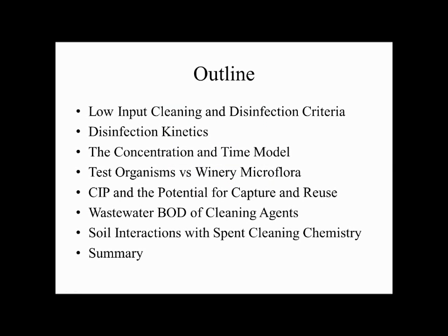Talk about the organisms that are typically used in cleaning sanitation chemistry versus what we're interested in winery microflora. Talk about clean in place, and clean in place is a technology that a lot of wineries and small wineries say that's well beyond what we need to do. It's only for big places. What I'll try to explain to you today is that actually it's probably more beneficial in small places, because you really want to be able to capture the water after you've cleaned the tank and not have it go down the drain. And the essence of being able to do that will be having a cleaning system that lets you capture the water before it goes down the drain so you can reuse it.